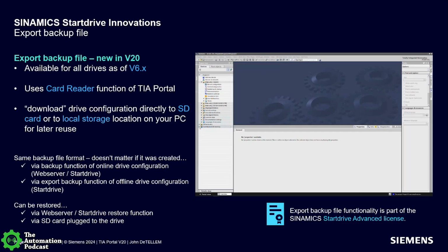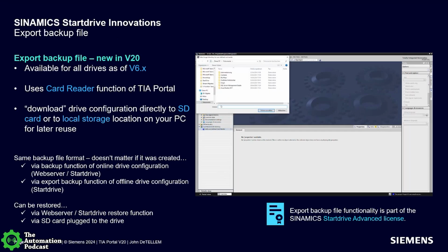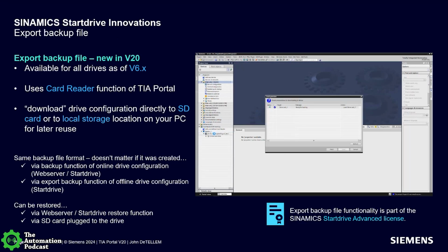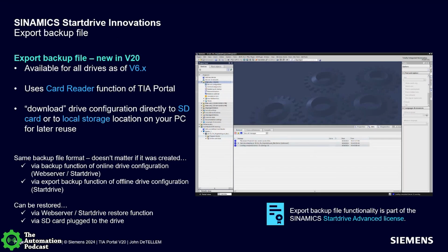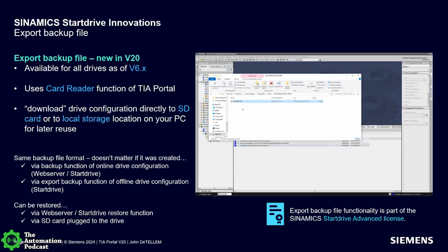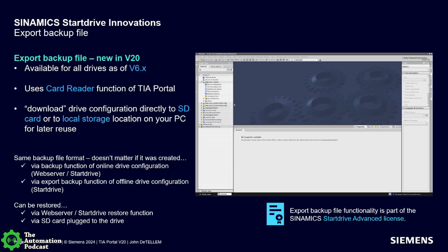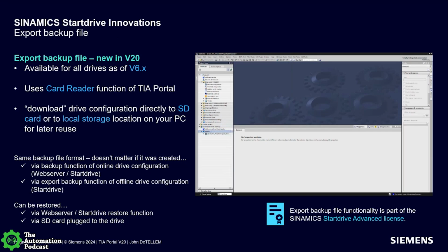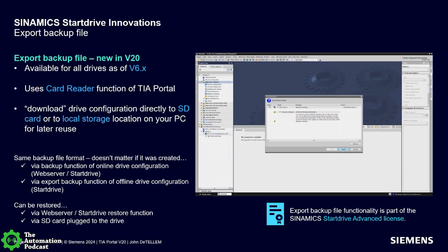It's a powerful maintenance thing to understand these kinds of tools. Yeah, we covered it in my course. I think it's very powerful. We cover how it works with both the 1500 and the 1200, with a bit more limitations depending on which one you use. But of course, with the 1500, you have to have that card, so it has to be a Simatic card. But very powerful and something I think other vendors wish they had. It's a real cool feature. It is, it's amazing. I change out the hardware device, pull the memory card out of it and put it in the new device, and it starts back up in run mode with just putting the card in there, because the card contains the full operation of that PLC.